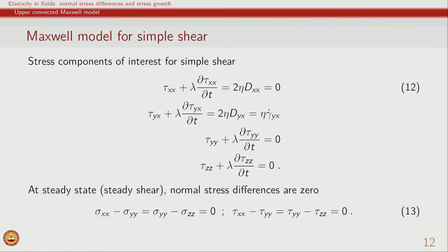So, the nonlinear counterpart of the Maxwell model arises when we use the correct form of stress rate. The statement of the Maxwell model is that the stress and the stress rate are related to the strain rate in the material, and for the stress rate we are using the partial derivative.